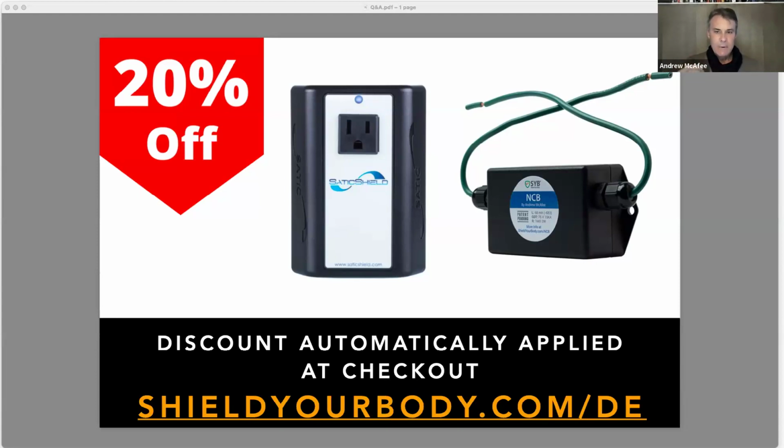SLT, buy their orange micro amp meter. You spend $150, but you get a great device that even electricians aren't going to have the sensitivity. So all you got to do is clamp over a wire, and if it's carrying current, this thing can measure down to microamps, and that's what you want to do. So that's probably the best tool to use.